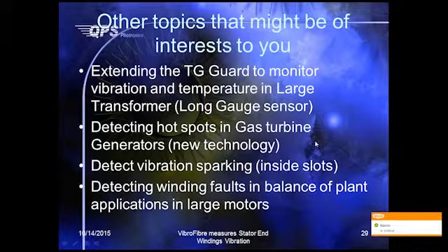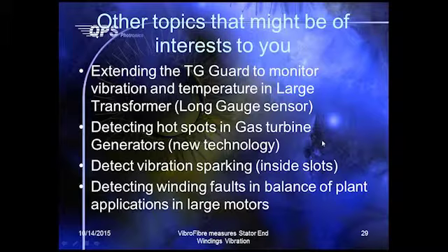There exist methods to identify them, but these are very expensive, cumbersome, and use thermal imaging. When you introduce a magnetic field, you physically see the eddy current causing the temperature rise. So again, we use another adaptation of the cavity, and we now have a means of measuring hotspots and identifying which winding has it.